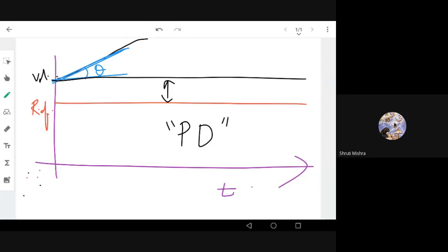At least why? Because derivative control only acts on the change of the error. Right? So if the error is not changing, it is constant, and the derivative controller will not do anything. So the error will be the same. Error will be constant. So there is no changing error. So okay, I always should use a proportional controller along with the derivative controller.